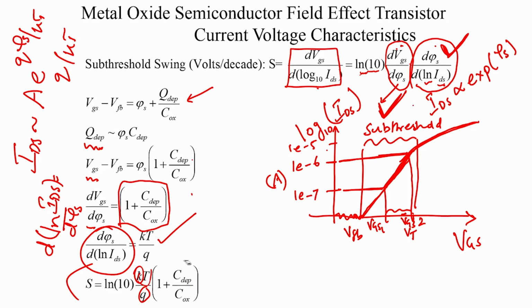Although we have still not defined these things, you will realize that more parasitics start developing in the device. For example, the interface between the semiconductor and the insulator will have interfacial trap charge. All those regions will trap charge and add on to the charge present in the semiconductor. So, any parasitic capacitance that traps charge or contains charge at the semiconductor insulator interface will add on to these terms in the numerator, and all such parasitics will effectively start increasing your subthreshold swing and decreasing your subthreshold slope.